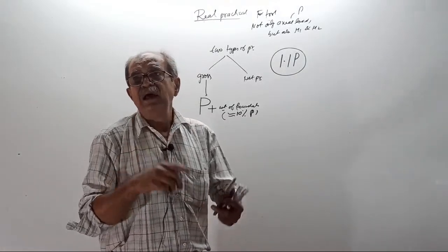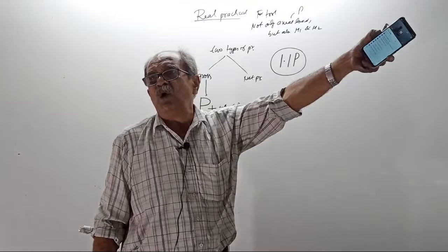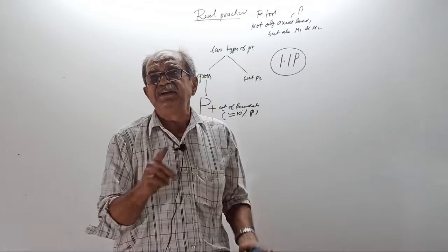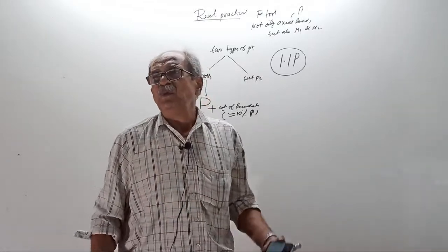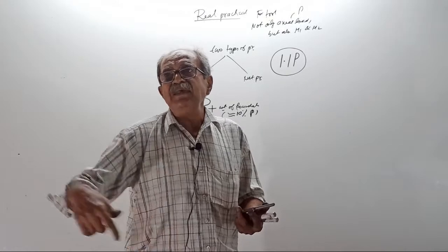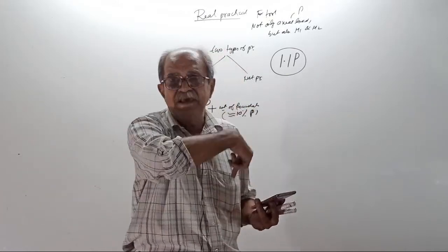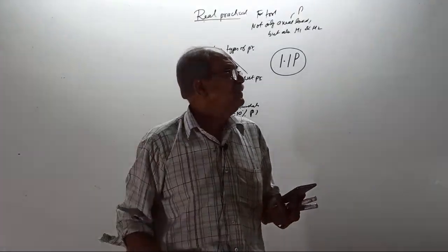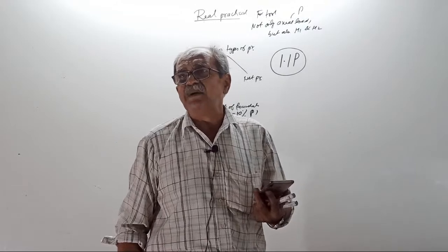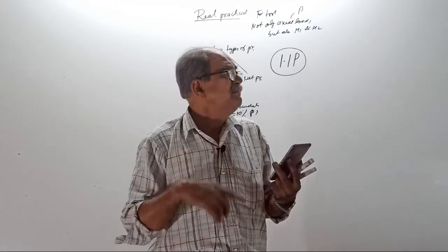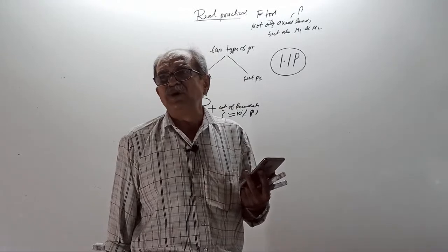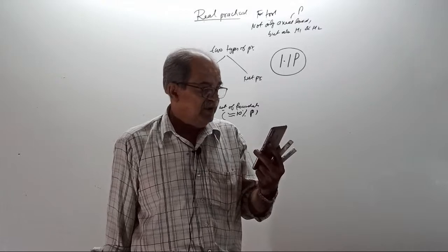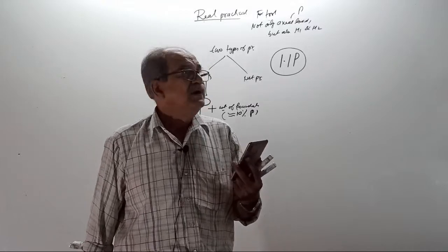But remember, when you go for the ETABS and SAFE model, you don't consider self weight of footing. Tell me why. Reason. When you model, you are giving the lengths L1, L2, how to give will come now, and you are also assigning thickness of footing slab. Therefore, self weight of footing slab, you don't tell SAFE. Why?